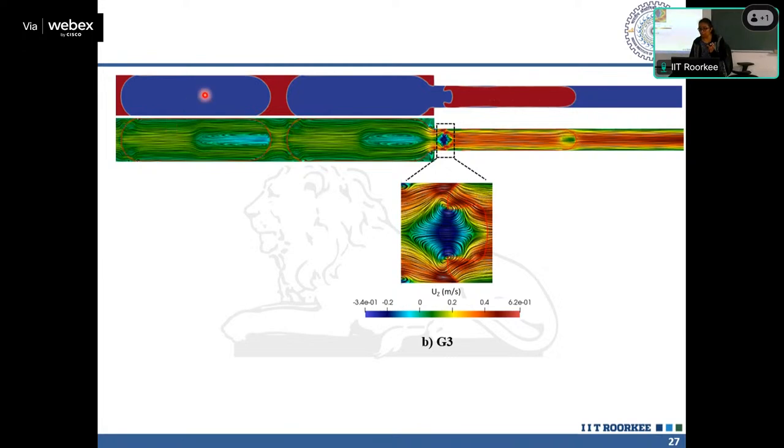So this blue part over here, which is forming a slug, as it enters and feels a change in wettability, you can see the presence of a continuous medium, and gradually the continuous medium over here forms the dispersed medium, due to this role reversal at this point. And of course, there is also the presence of vena contracta. So you get to see a recirculatory zone which further enhances the formation.